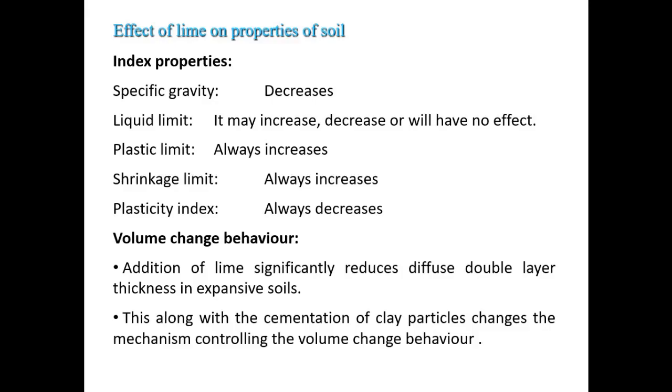When the reduction in the liquid limit due to cation exchange is balanced by the increase in liquid limit by flocculation, there is no effect on the liquid limit. For kaolinitic clay, since it is already flocculated, no effect on liquid limit with lime. The number of monovalent cations in the soil influences the cation exchange capacity.